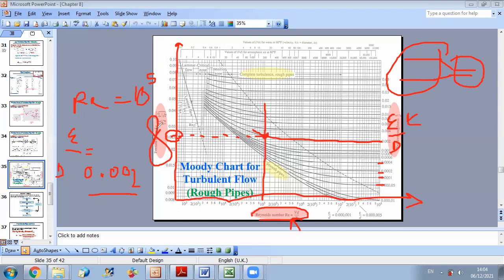So the friction factor will remain the same as long as the Reynolds number and epsilon over d are not changed. So if you have one circular duct of constant diameter, then you can find one friction factor for the whole duct, of course if you consider the case of a fully developed flow, so V average is not varying.